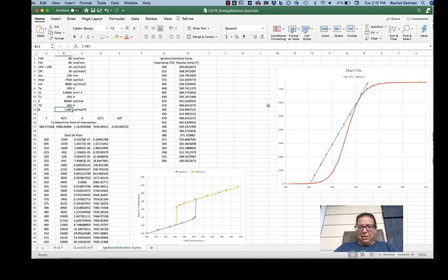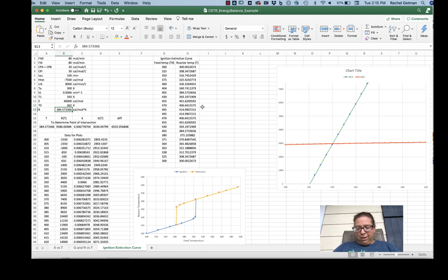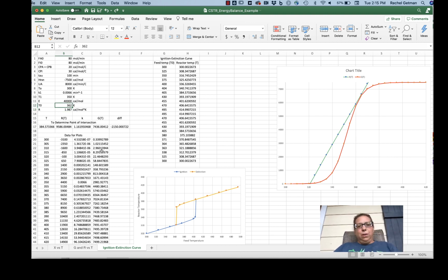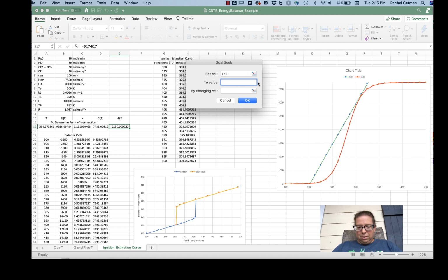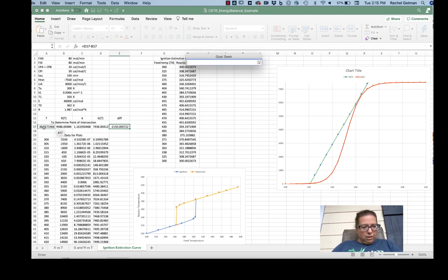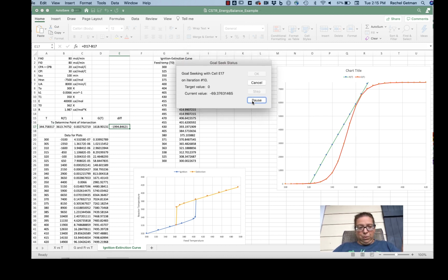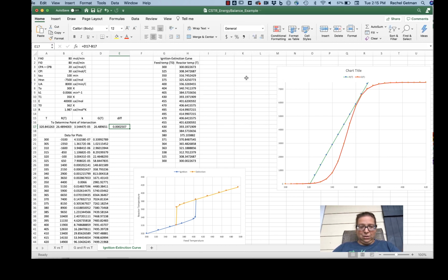And we looked before in the last video, and I think we said that was 362. I actually found in this video that it wasn't 362, it's 364. I don't know what happened there. Okay. So the way that I found that was, I put 362 here, and I use my goal seek function. And I'm giving a guess of 384 Kelvin, which means, if there is a solution near 384, it should find it. But what I find out is that after a lot of iterations, it goes down to 320. So that tells me, okay, there probably isn't a solution for this feed temperature on the upper steady states.